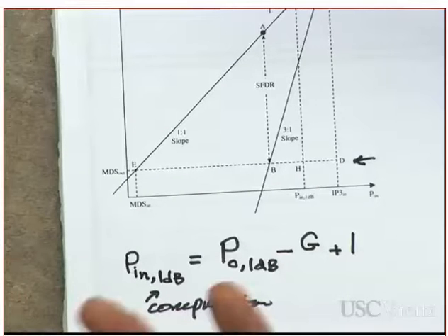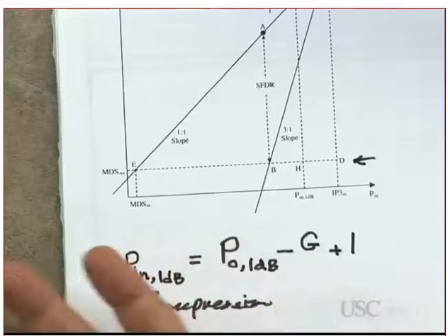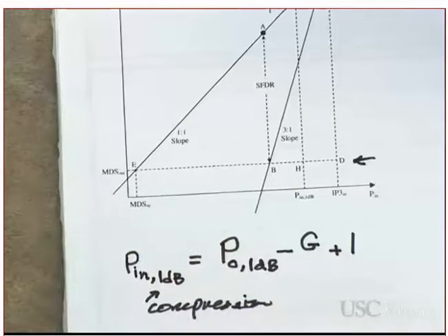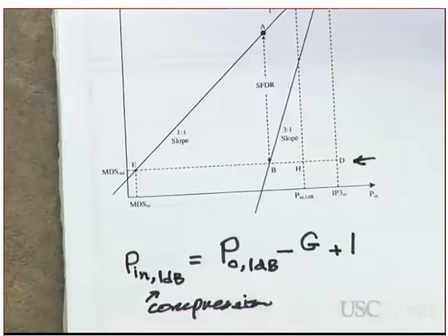But if the question gives you the signal to noise ratio, as I will show you in just a second, then you need to take the MDS rather than the noise floor in calculating the dynamic range.